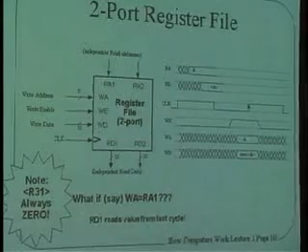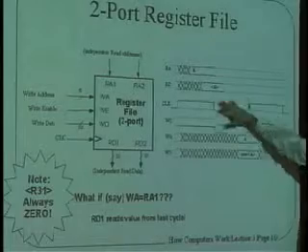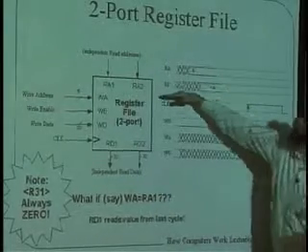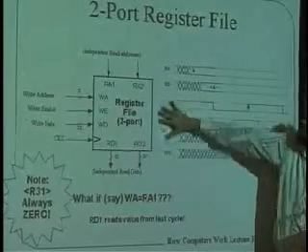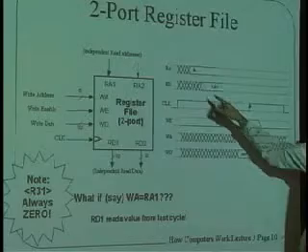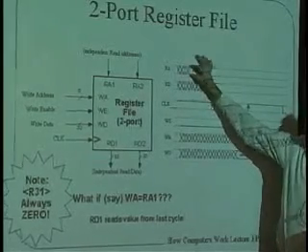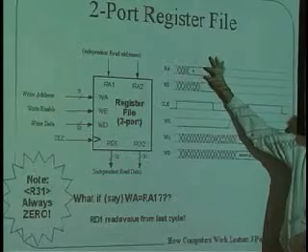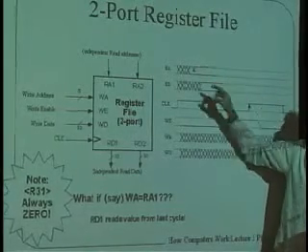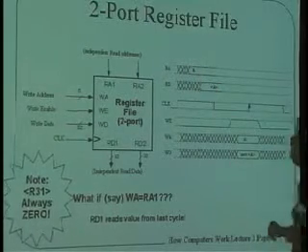And so let's take a look at the timing diagram now and see if we can understand how this thing goes. First of all, the clock here is going on and off and on and off, but that has nothing at all to do with what's happening in these first two lines. So I want you to think about all this stuff down here as not making any difference for the next minute or so. RA has some indeterminate value that we don't know, and then finally it settles down to either a high or a low on any of the 32 bits that it has, and the value that it has is A. A is an address.